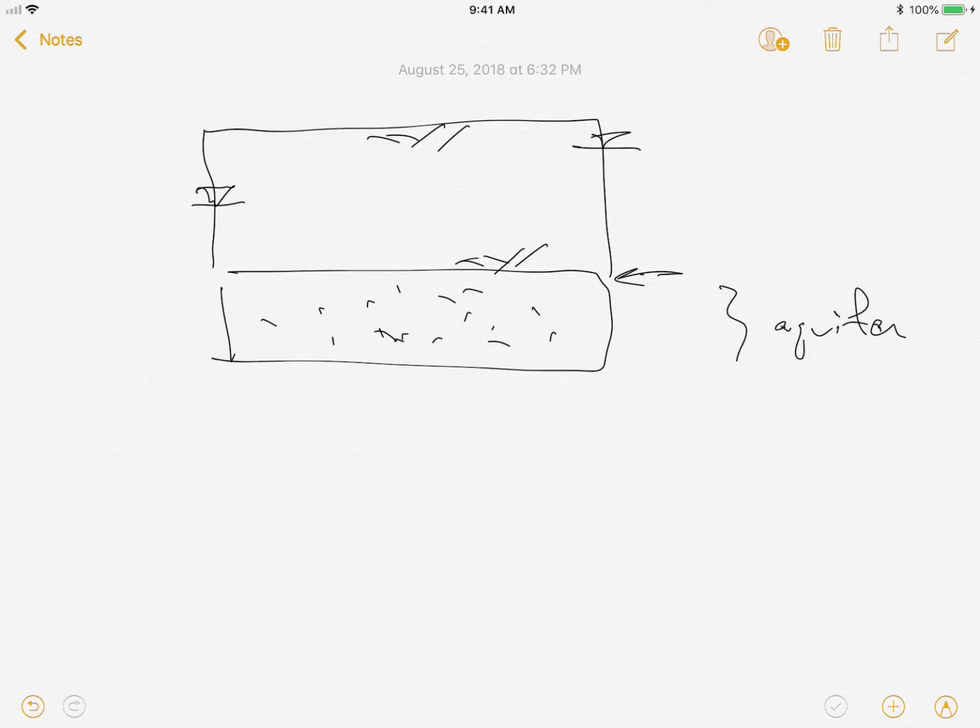We are going to look at an aquifer with three different types of materials. This material over here, we're going to say is clay. That's not typically an aquifer, but we're interested in seeing how energy drops through different materials. This is really important because as civil engineers, we can manipulate energy based on the type of material. It's a little complicated because you'll ask, how do we determine what's what? But we're going to make simplifying assumptions just to understand how energy drops through different materials. Then this material over here is going to be silt, and this is going to be sand.